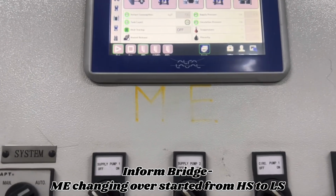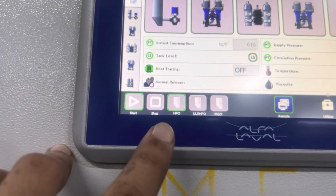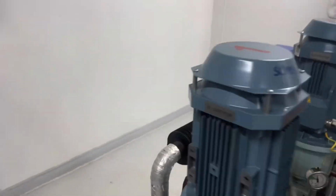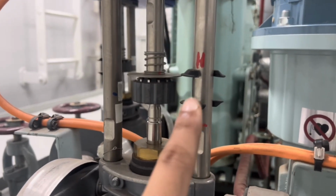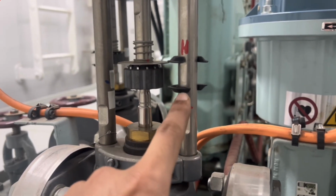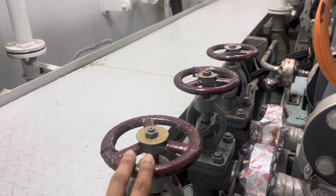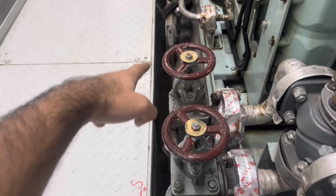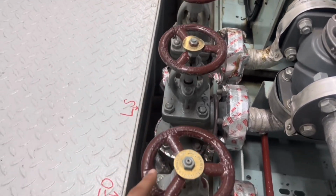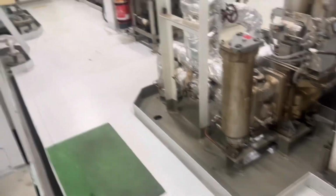So guys, this is the panel for the main engine changing over. So now we are on the high sulfur. Here you can see we are on high sulfur. So before changing over, make sure the valve is open. So on the ship we are keeping all the three valves, diesel oil, low sulfur and high sulfur, all the valves open, and now we can proceed.